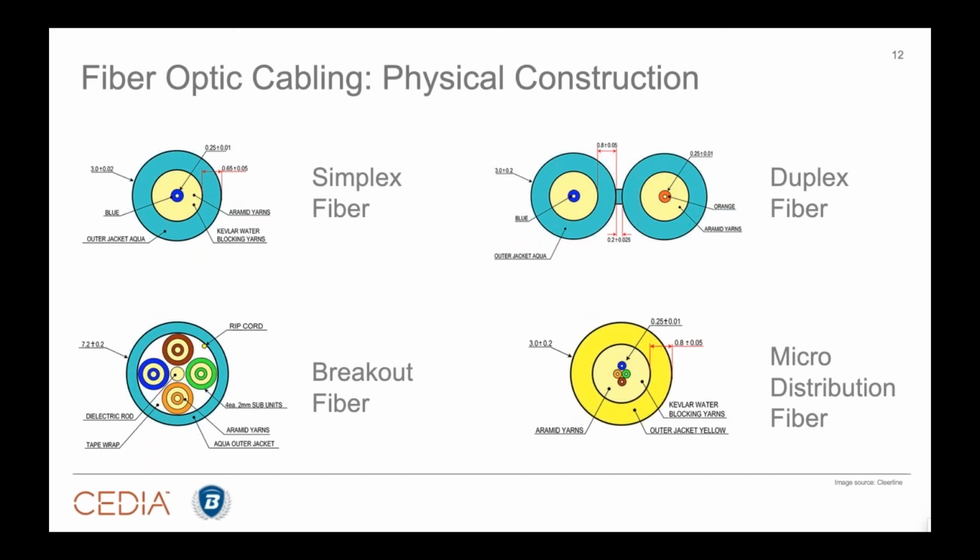And that is because, as I just mentioned, most electronics use one strand to send and one strand to receive. It's actually less expensive when you build your electronics to do that. You have less processing, less optical engines. Less optical engines make the electronics less expensive. And if you've ever looked at the SFP port, the fiber port on a network switch, you'll notice it's got two connections. One side sends, one side receives. You need duplex fiber. So even if today you only need one piece of fiber, pull two. It'll future-proof your run. You will not regret it. Make sure as you are helping your customers wire their buildings, their homes, you pull two fibers.